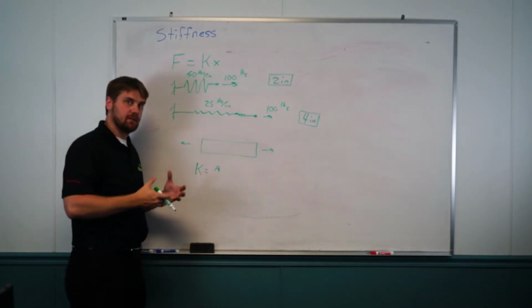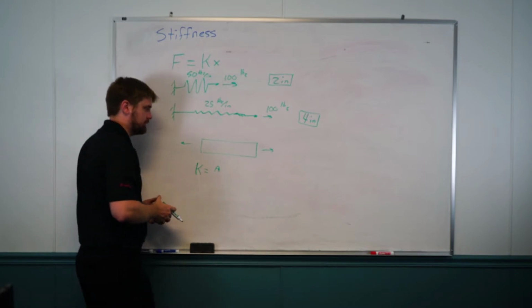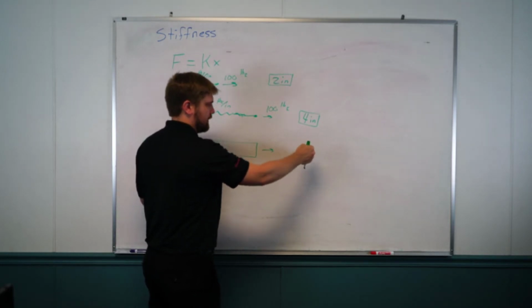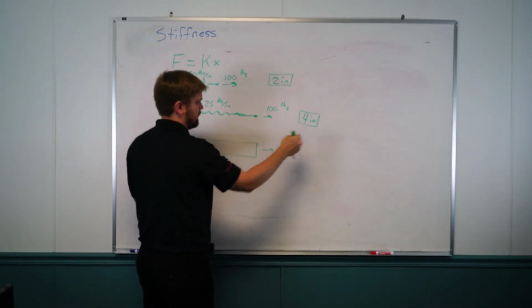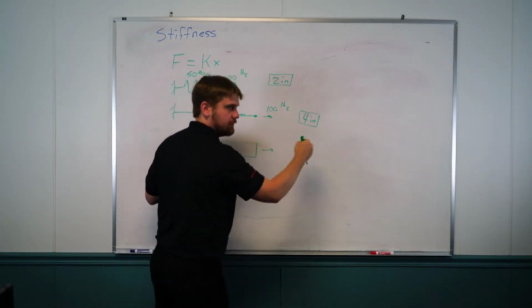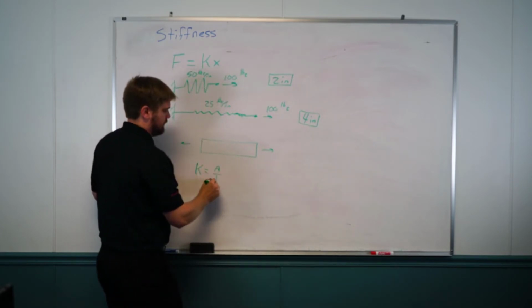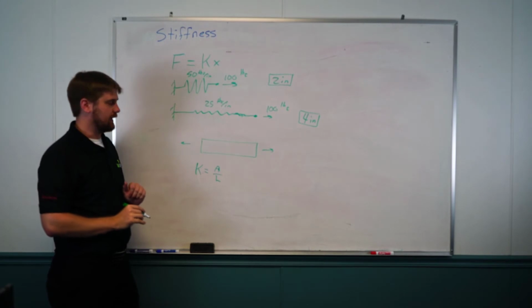It's twice as much material that can take on that stress. What about the length? Well, if you double the length, it makes it more flexible. It's like having 2 of these bars both deforming, contributing to that displacement versus just one of them. Stiffness is inversely proportional to the length.